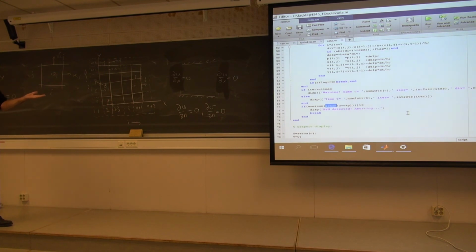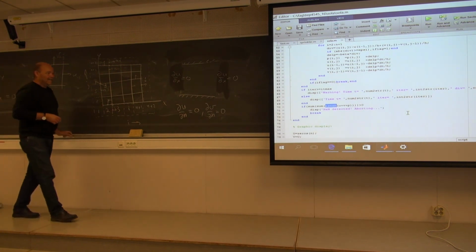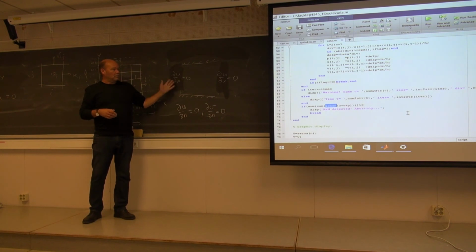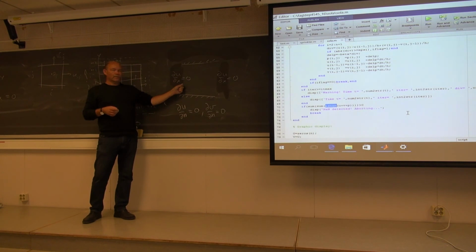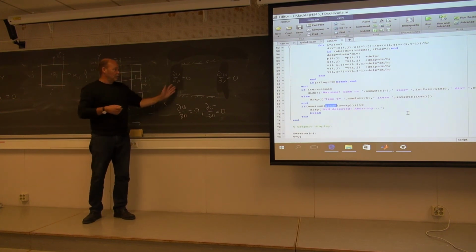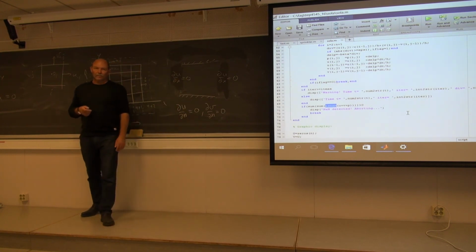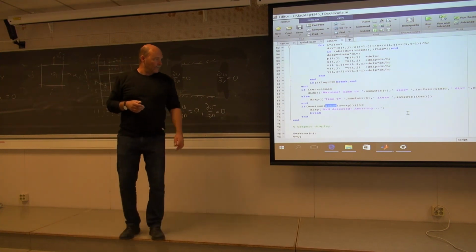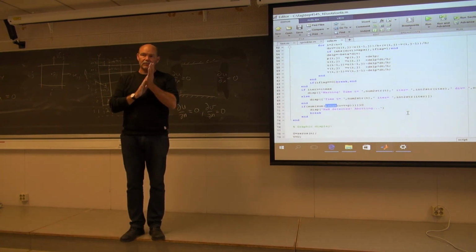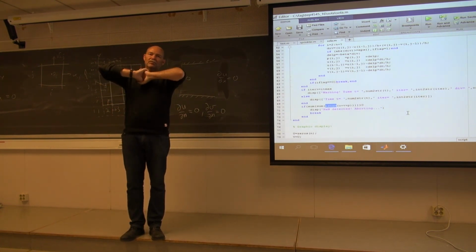But I don't have a driving force in the problem. No pressure difference, no gravity, and I don't say anything about the inlet velocity, so probably I will get just the zero, no-flow solution here. But I don't know. Try, see what happens. So it's not always easy to see what's the proper boundary condition for a given problem. What can remedy that is experience. So start exercising.